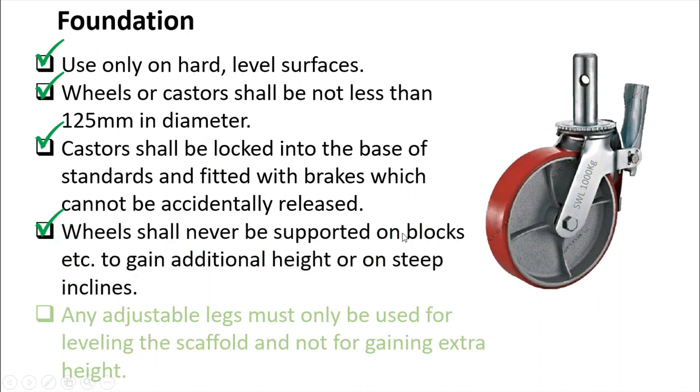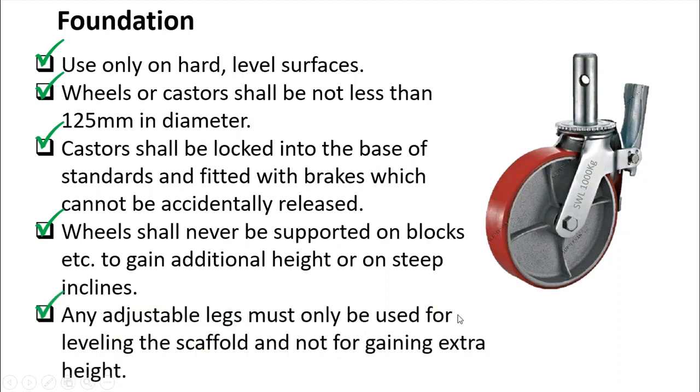Caster wheels shall never be supported on blocks, etc., to gain additional height on steep inclines. So you cannot put some blocks underneath this caster wheel to make it level, because it will give you an unsafe condition and it will trigger an accident. Any adjustable legs must only be used for leveling the scaffold and not for gaining extra height.